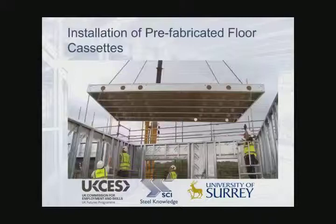Here we see installation of a large prefabricated floor cassette, in this case of the order of 4 meters span, in which the C-sections have preformed holes for servicing, and you can see in the foreground the bolt holes used to connect the panels together, and also the bolt holes in the background used to connect to the external wall panel.